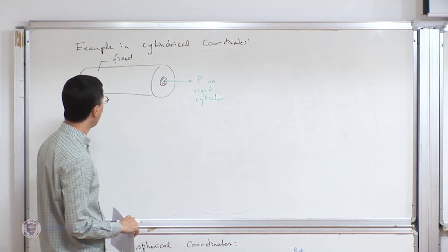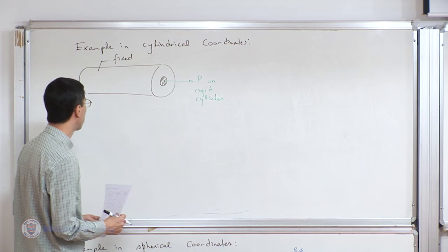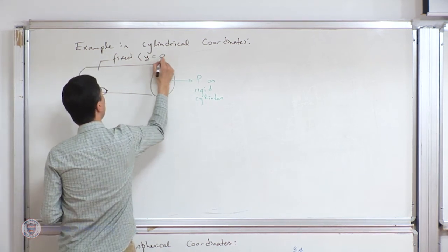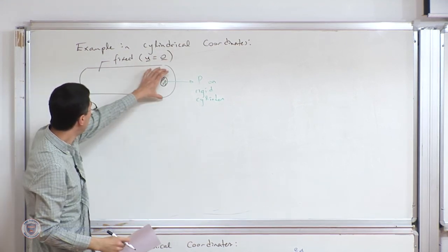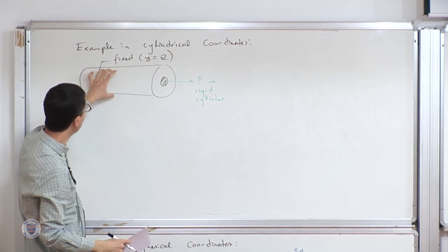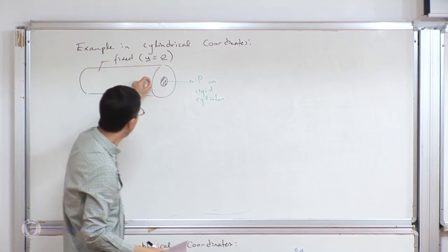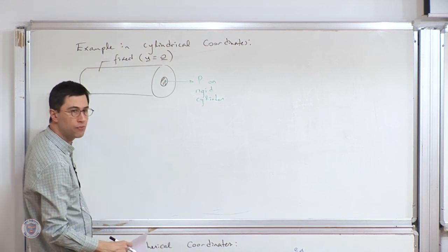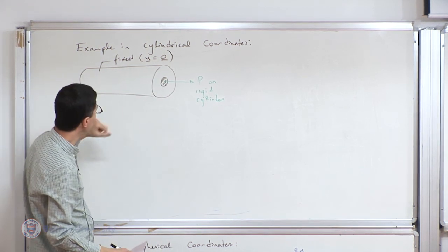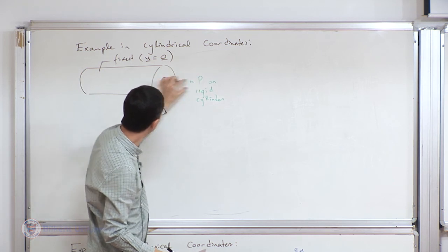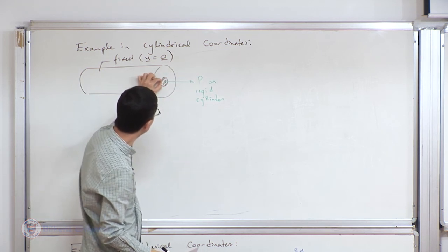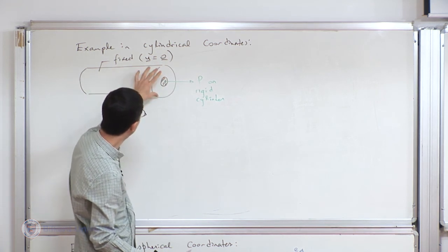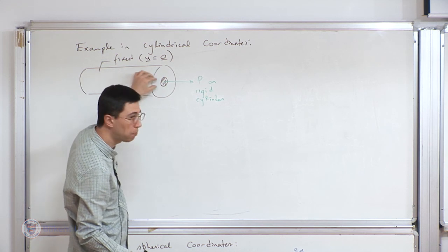Okay, so I just put a tensile force. All right, so fixed means, by the way, that displacement is going to be zero. So the outer surface of the cylinder is entirely fixed. It doesn't move anywhere. On the inside, I am pulling with a force P. And on the left, it's free, okay? I have nothing. And so when I pull, this inside rigid cylinder is going to try to move outwards. I'm holding the outside fixed. So this surface and the material inside somehow needs to partially move with it.